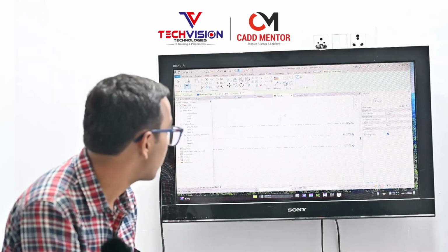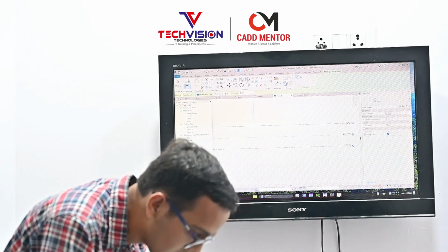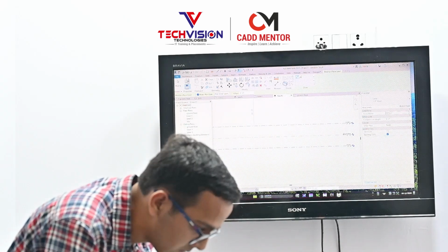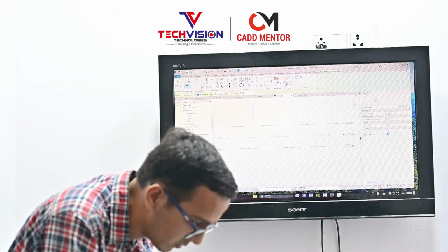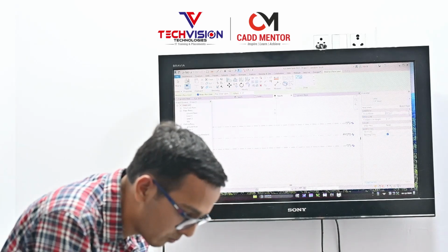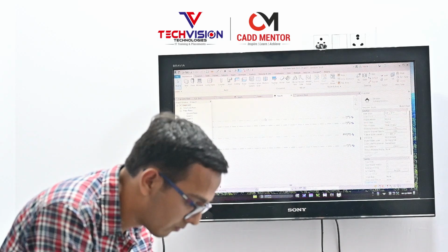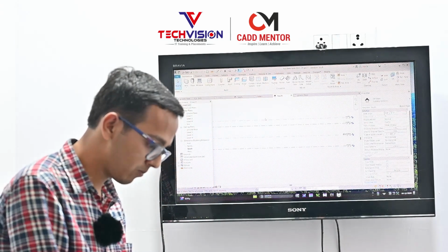And then alternately select the levels, and you could give the point out. There's 5 feet 6 inches, 5 feet 6 inches, and select the pick point and click on it. So here we basically make the 4 levels for this project.